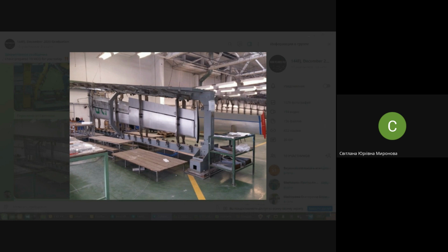What is next? Actually, the skeleton is a very important portion of the jig, but it's not the element that we really need for locating, for providing interchangeability and coordination of our aircraft pieces, aggregates, units. The most important element in a jig is the locator or system of locators. In those jigs that you see in front of you, we see locators, some of them still closed, couples of locators that might be called fixing arms in some literature.